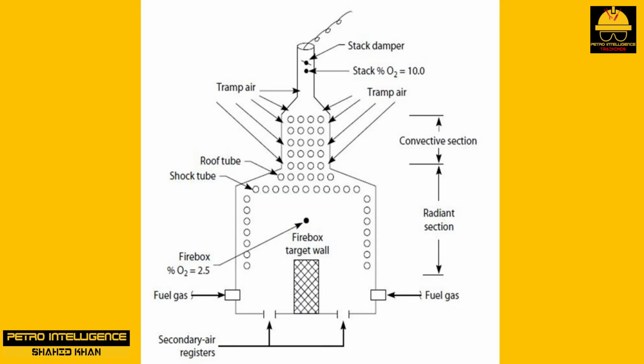If we operate with a positive pressure in the firebox, although the burners may appear to operate normally, the hot flue gases will leak outward. This damages the roof arch supports and the steel structure so as to shorten the life of the heater. Flame impingement of the upper radiant tubes may also result from positive pressures.